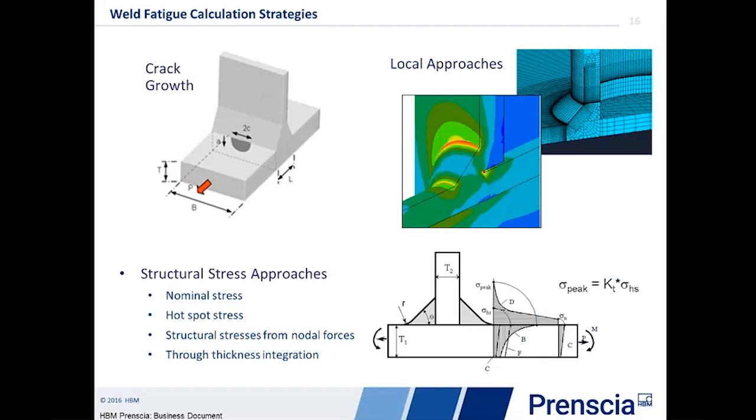Also, the crack growth rate is a function of the crack size, such that we can't go off and leverage things like Miner's rule. We actually have to solve this iteratively to failure. So, though it would be the ideal approach for looking at the behavior of the welds, it's not really ideal for applying it to a whole structure and a large portion.